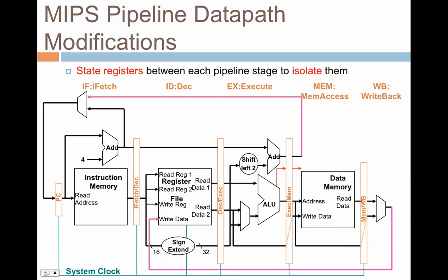Now here, you should also see that this sign extender also goes to shift left by 2, and it goes to another ALU, and we compute here the effective branch destination address. So the sign extender goes to the shift left by 2, and we add it to the PC plus 4, and that value becomes the value on the branch. Whether the branch is going to hit or not is the zero signal that I showed before, and that signal appears here. So once we know whether it is zero or not, this signal will be used to control this multiplexer, which is going to choose between PC plus 4 or the branch destination address.